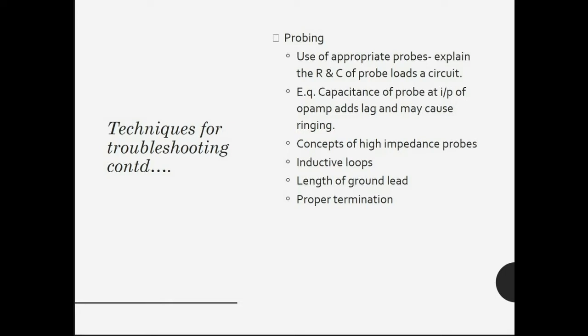The 10x oscilloscope probes also allow some compensation for the frequency variation present. A capacitor network is embodied into the probes as we refer to the circuit diagram. The capacitor connected to the ground can be used to equalize the frequency performance of the probe.